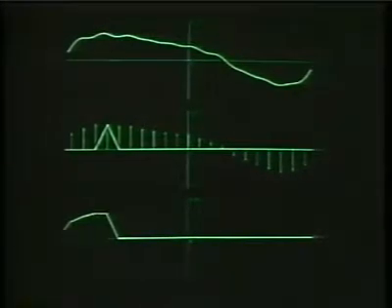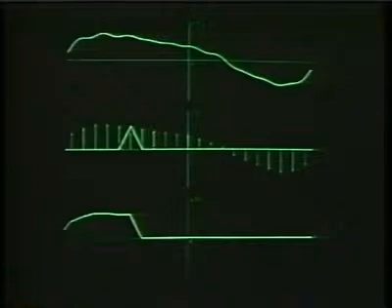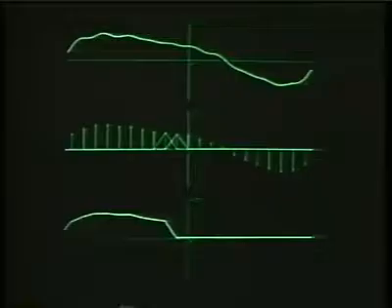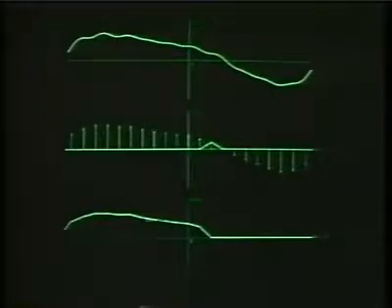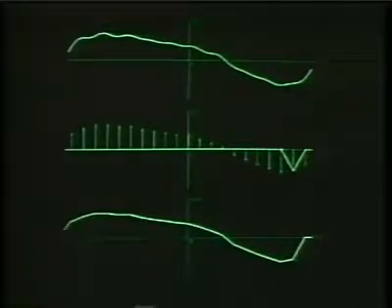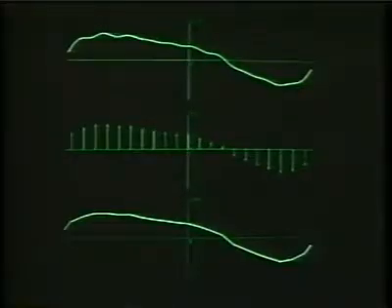We add that in. Then we'll speed up the process, and as we proceed through, we are building basically a linear interpolation in between the sample points, essentially corresponding to, if one wants to think of it this way, connecting the dots. And what you're watching once again is essentially the convolution process, convolving the impulse train with the impulse response of the interpolating filter. And what we're generating then is a linear approximation to the band-limited continuous-time curve at the top.